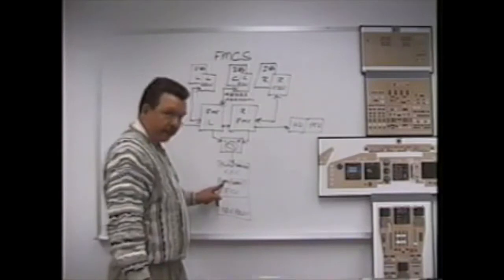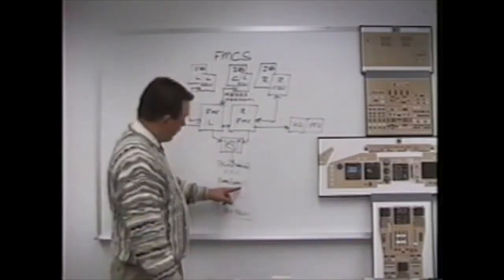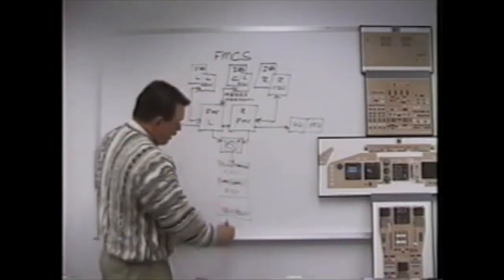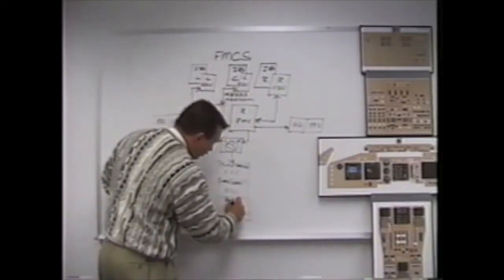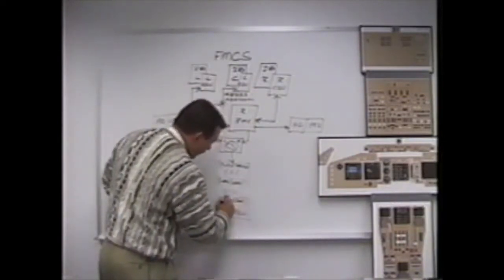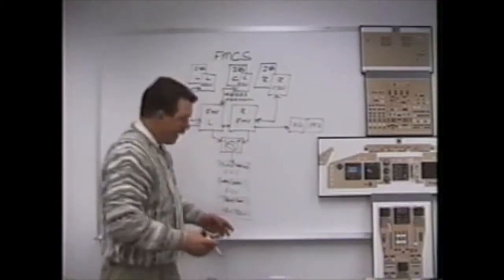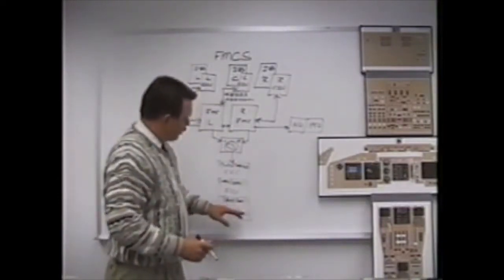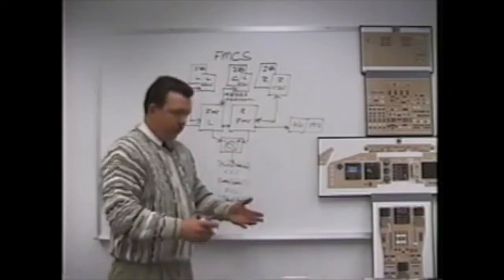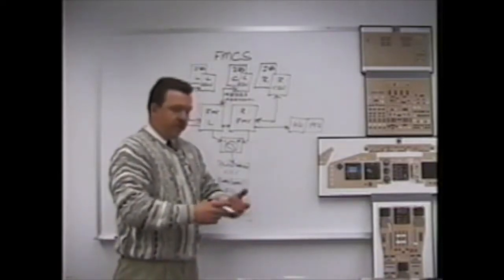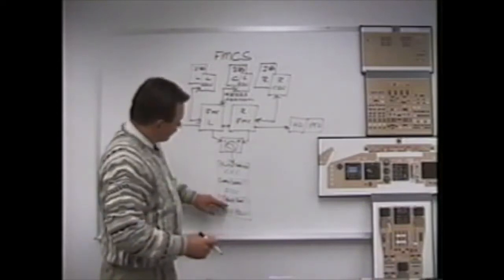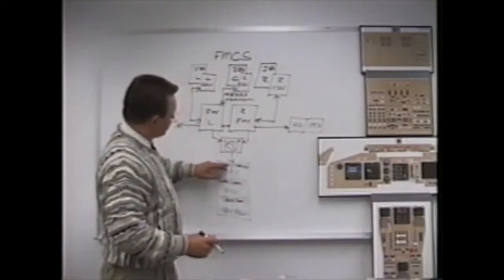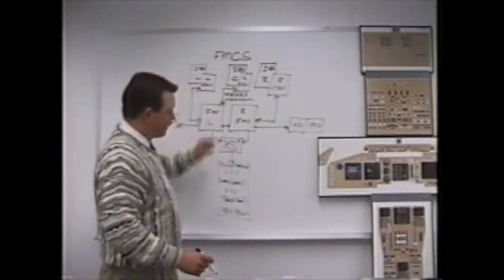When to turn left, when to climb up. And when I climb, set climb power. The nav radios, what to automatically tune them to, auto tune. So if you don't have the nav radios manually tuned and you've got them in the FMCs able to tune them, the FMC will automatically tune it based on a route, a procedure, or automatically for updating purposes like we talked about. But the auto tune, the LNAV, VNAV, and the auto throttles get their signal from the selected FMC.